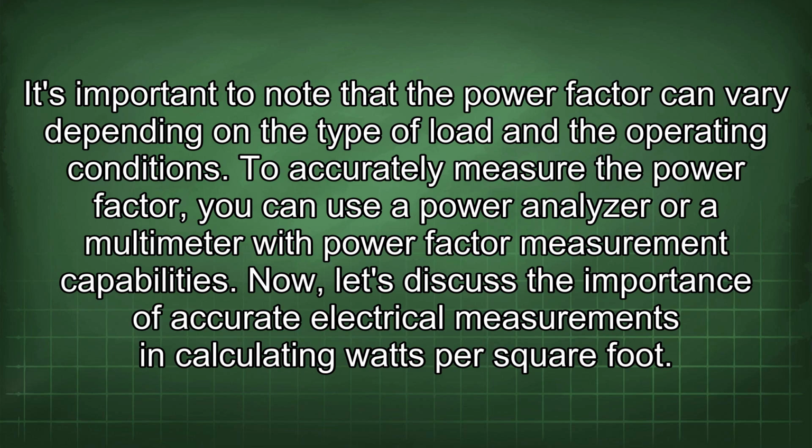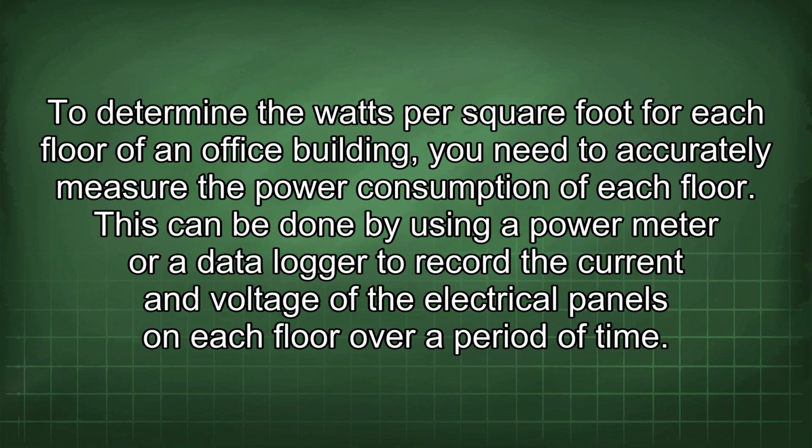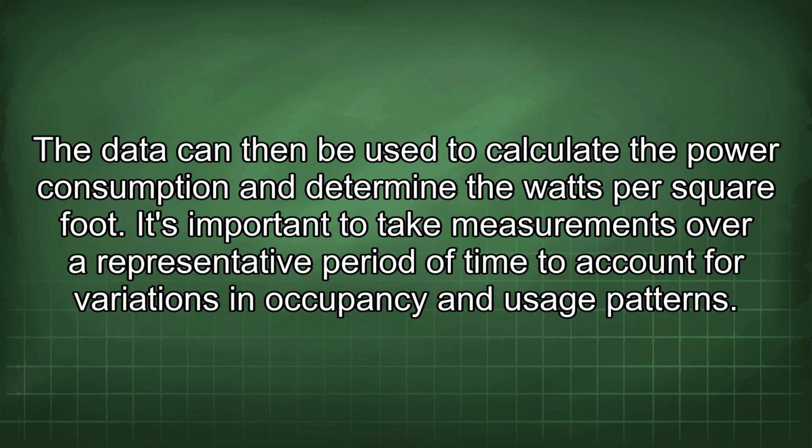Now, let's discuss the importance of accurate electrical measurements in calculating watts per square foot. To determine the watts per square foot for each floor of an office building, you need to accurately measure the power consumption of each floor. This can be done by using a power meter or a data logger to record the current and voltage of the electrical panels on each floor over a period of time. The data can then be used to calculate the power consumption and determine the watts per square foot.